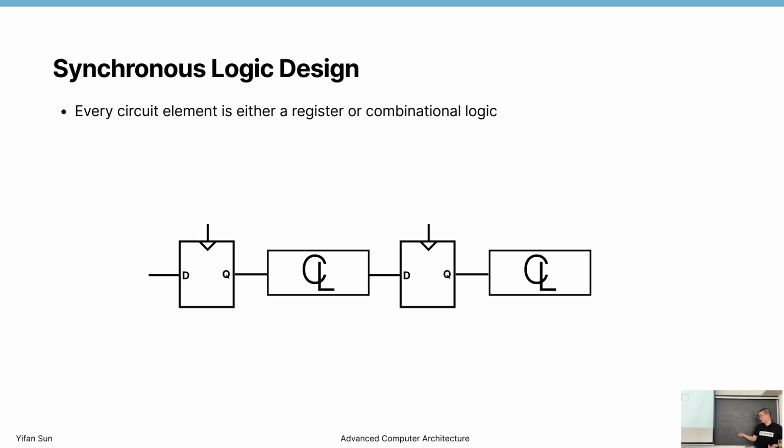Because they want the clock frequency to run faster and faster, but they have too much logic to finish. Then there's a trade-off: do you have more stages, or fewer stages where each stage takes longer? So this is a design parameter: if I want to run at 1 gigahertz, I have to sacrifice the capability of each clock cycle.